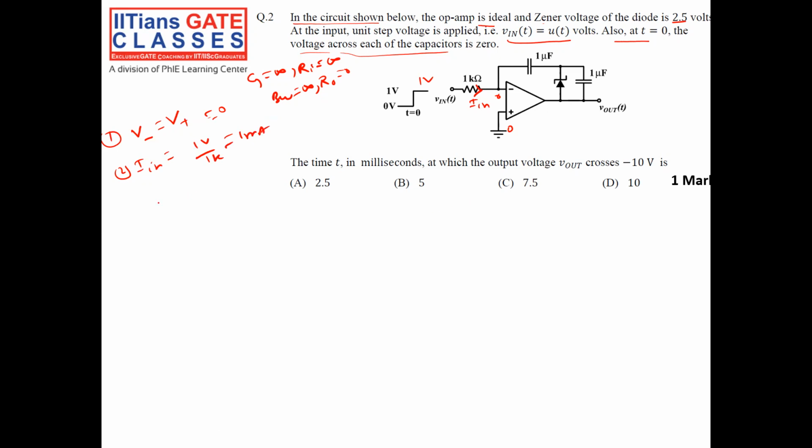Third step we need to understand is what? The Zener diode is a 2.5 volt Zener diode. So we have to know what is the characteristic of a Zener diode. So this is Vz, this is Iz, right? We know a Zener diode always operates in reverse bias. Since no minimum current is given for the breakdown, we will assume that the minimum current is 0, right?